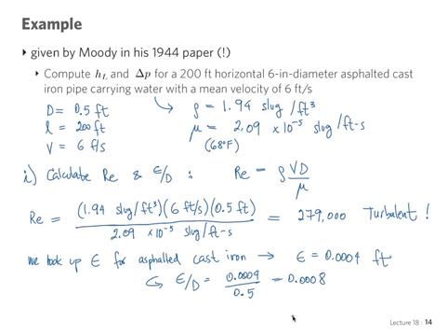So next we need to find the friction factor from the Moody chart. And I've actually printed out several copies of the Moody chart. I'm going to pass them around now, so everybody's got one. Okay, who's got the friction factor found and ready to spit out? 0.02. Already, we got some experts on.